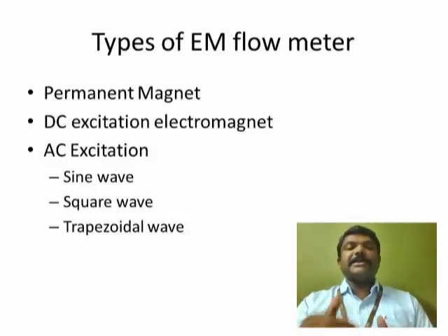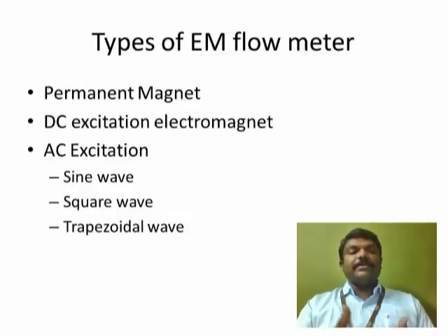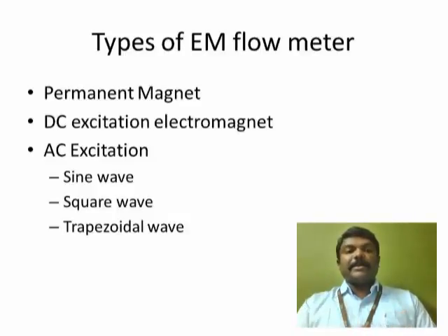The amplitude is higher than the signal of interest, and the signal of interest, that is the induced EMF due to the velocity profile, is less than the transformer voltage. So because of that, to remove the noise and get the signal of interest from the overlapped noise signal, we need to have high-end filters, and the total mechanism of the measurement technique becomes complicated.